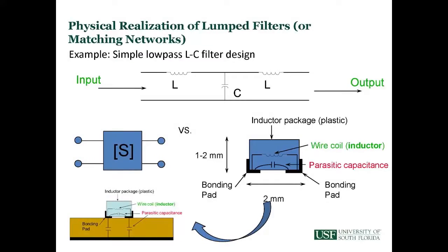So if we instead want to use a model, one of the things you can do if you have measured S parameters is you can make your own models if you systematically know what to do. In addition to the straight capacitance, if we put this on a board, there's going to be some ground effect due to the ground plane and the solder pad capacitance to ground. So the model starts looking a little more complicated.